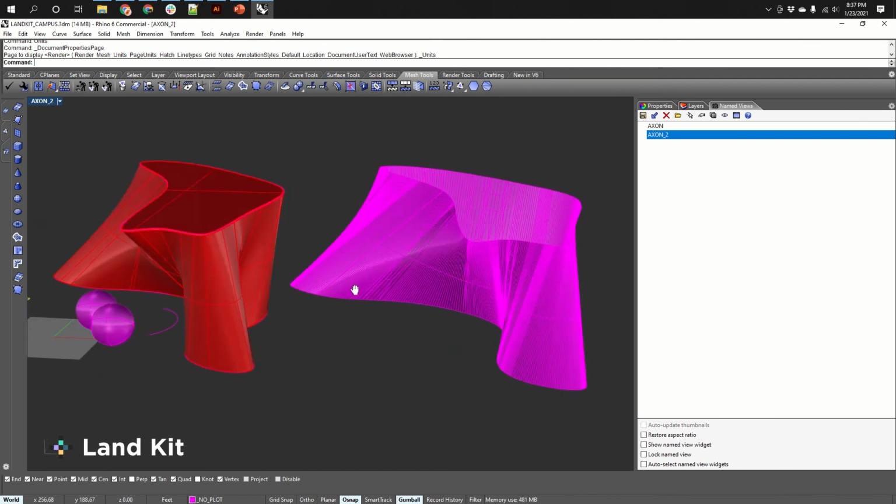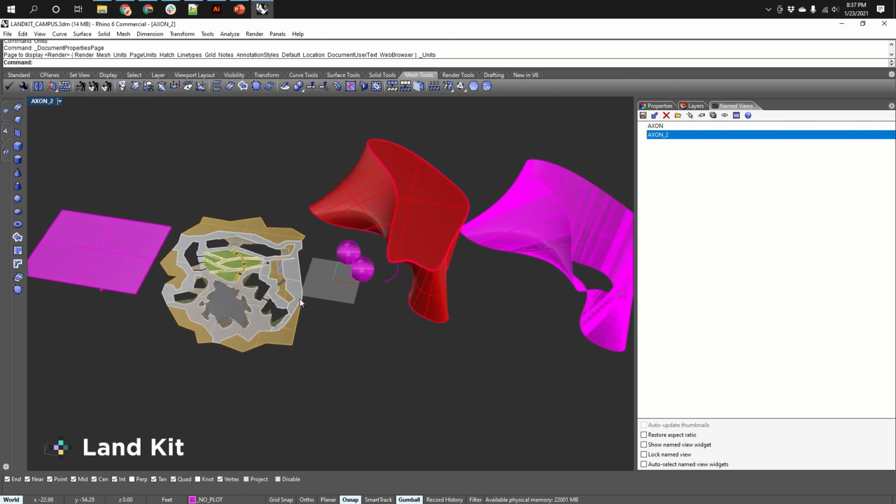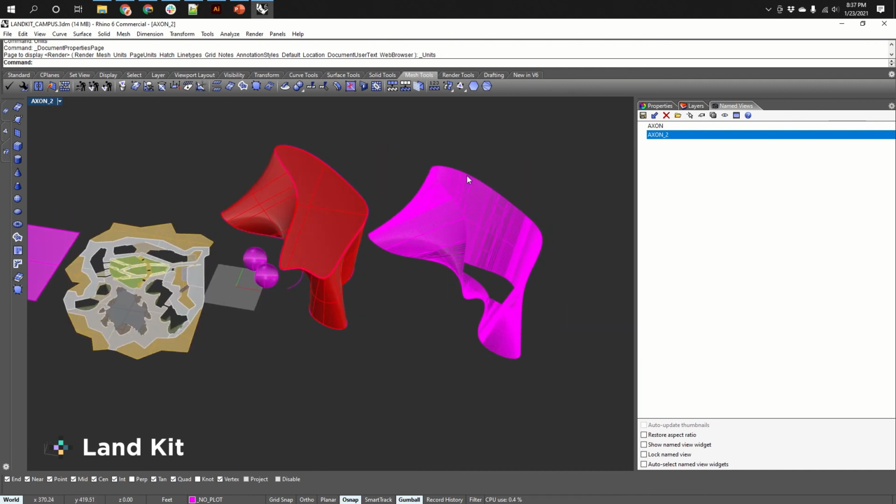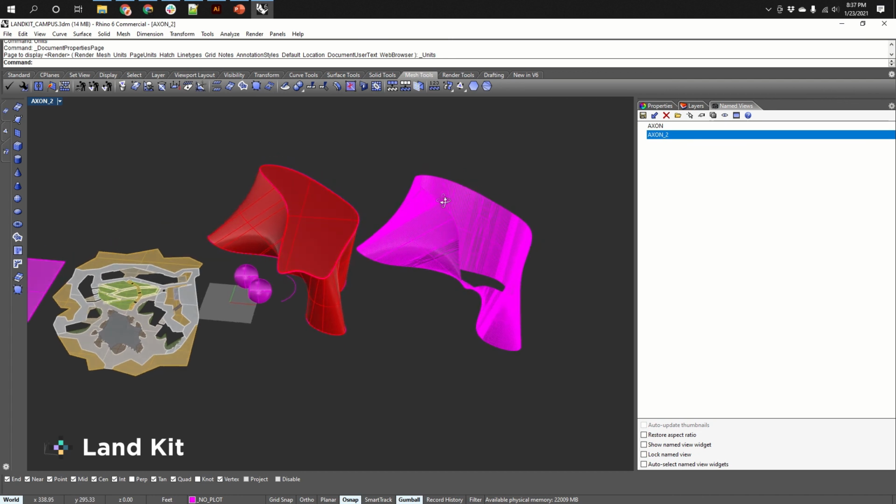And that's something to note. The trim tool that we used before works on surfaces and it works on curves, but it will not work on meshes. In order to trim a mesh, you have to type mesh trim. Okay, so that's giving you the general idea.